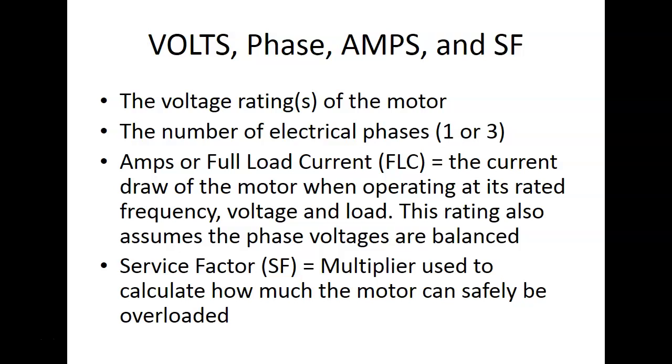Phases. We only got 2 phases over here. What's the phase we got? The phase. Our house runs on single phase. Heavy industry runs on 3 phase. So that's specified on the motor, right? The number of phases. What happens when you lose one of your phases? I hooked it up to the ground because we call that single phasing.